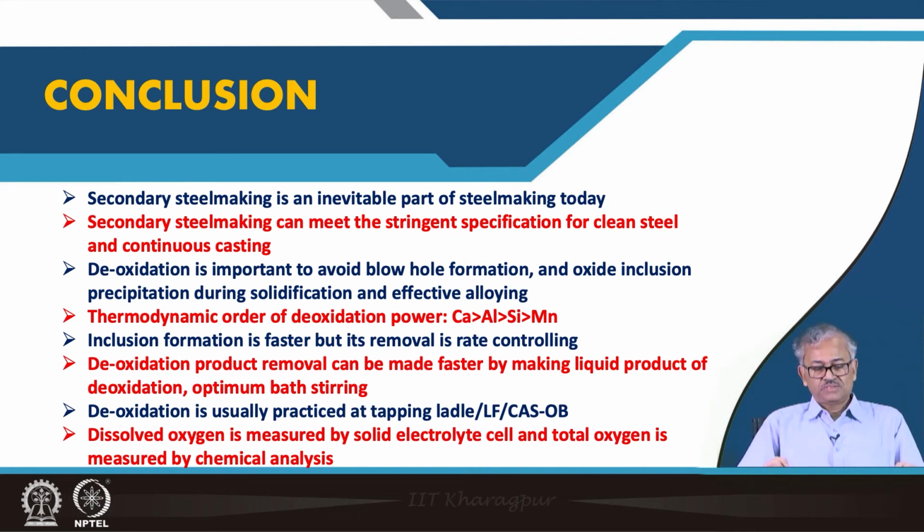And liquid products of deoxidation are very good from the kinetic point of view, for removal of impurities, because they coalesce, form bigger inclusions and go away from the system, right. So, as we have seen, inclusion formation is very fast, but removal of the inclusion from the liquid steel is not that fast; it is the rate limiting step. So, we have to concentrate on how to remove this inclusion as fast as possible during this processing time.